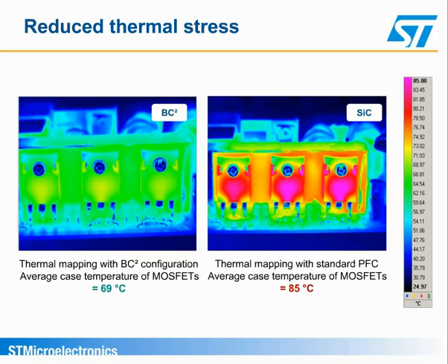When this junction temperature is reduced, the RDS on is also reduced, reducing the forward losses. A positive loop is then triggered. Temperature reductions of up to 16 degrees Celsius have been found compared to standard topologies. This can help to increase the MTBF of the device or can be used to reduce the size of the heat sinks.